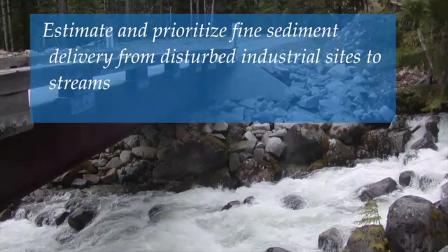In other words, if you are going to do a spraying program of herbicides in an area that isn't subject to surface erosion and without the ability to be connected to the stream, then it is impossible for that material to get into the stream. So there is a difference between mere proximity to a stream and actual location of disturbed mini catchments with direct surface connection to a stream. The important thing would be to avoid spraying within designated mini catchments in order to avoid that material reaching the stream.